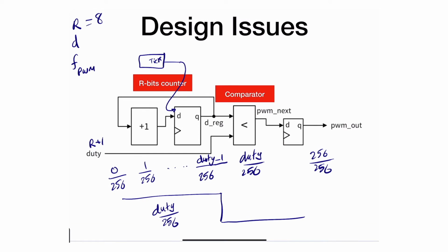So the first issue is that there's no way to provide the frequency for the pulse width modulated signal. The second issue is the duty itself: I will never be able to reach 100%. Now I will be able to reach 100% if I allow duty to increase by 1 bit, so I'll be able to provide duty as 256. And these are the 2 improvements I should add.